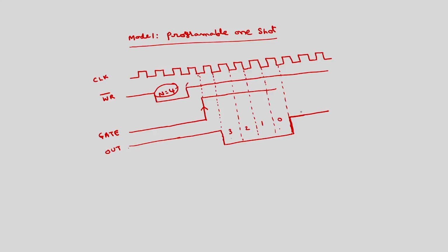Okay. Again this will be reloaded with n equal to 4. So, if I make this gate a low to high transition, again n will be reloaded with the same value and again it will go low for these 4 clock signals, and again go high. This process will repeat.